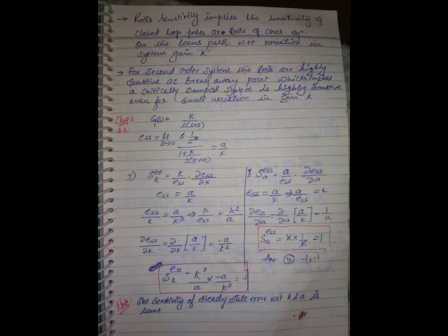To make the closed loop damping ratio unity means zeta value is 1. 2 into 1 is 8 plus 80 Td. From this you calculate Td. This comes out to be 0.2 seconds. So this is the derivative time required to make the closed loop damping ratio unity.